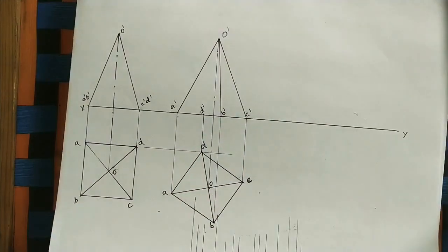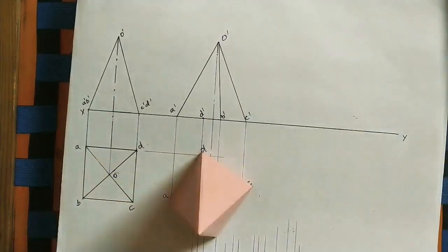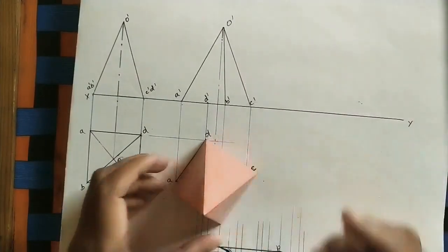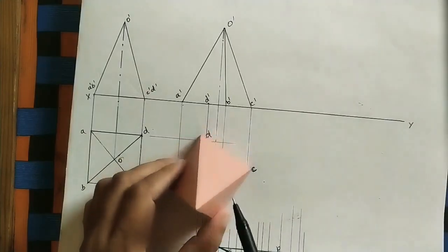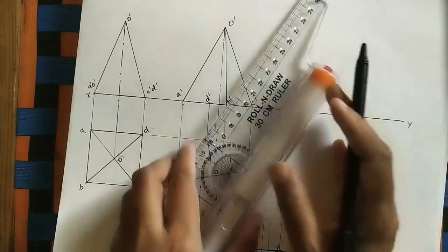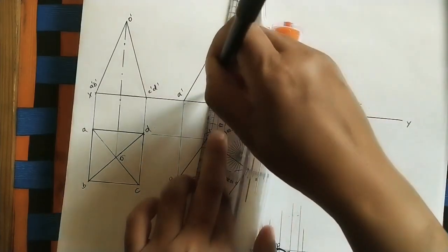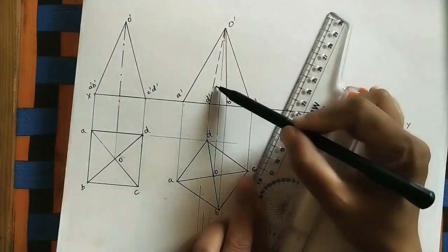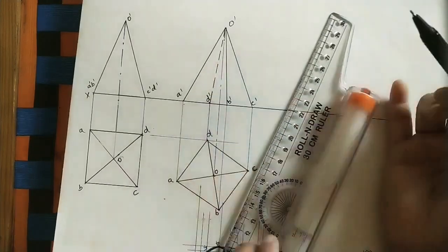Okay. Now if we take the solid here, like this, whatever D is coming from the front, from this front side, we can't see this D edge. Okay. So we can see this inclined edge from B. From D we can't see this edge. So whatever line is passing through D, it is a dotted line. So always remember, invisible edges are with dotted line. Dotted line means dashed line, like this. Always remember, this dash line should have equal length, and this gap is also of equal length at all places.